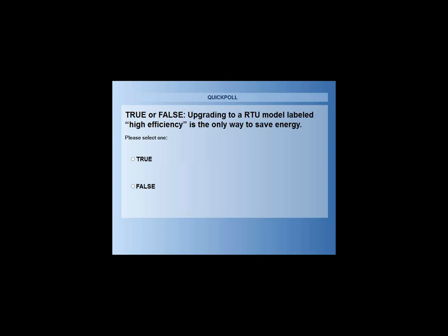Now, you don't have to go back to every single building you ever did and all of a sudden magically make them all comply with the current code. But if you are going to install a new rooftop unit or a new boiler system or add new windows or whatever, those things you're installing and the things that relate to them and connect to them have to be updated to the current code. So if you change out a rooftop unit and you put a new one in, and let's say the rooftop serves a classroom and it's more dense than 25 people per 1,000 square feet, then you are required to add a CO2 sensor to that classroom on that renovation project.